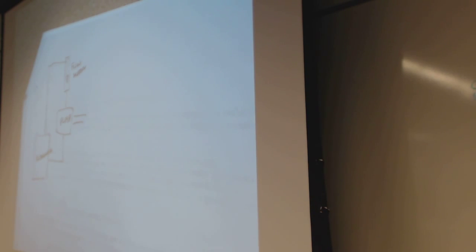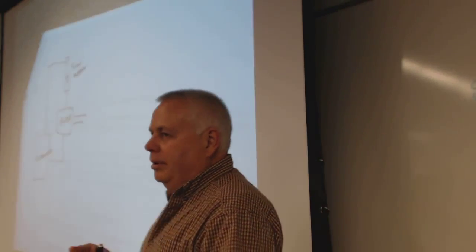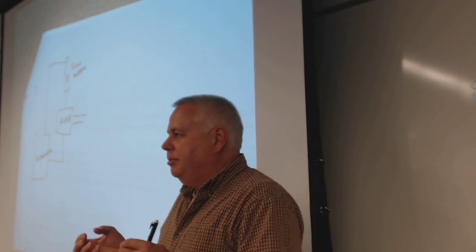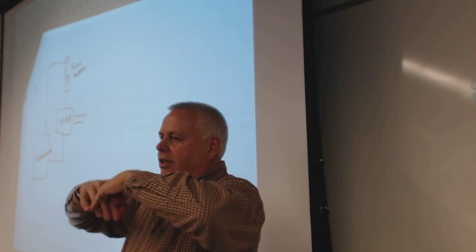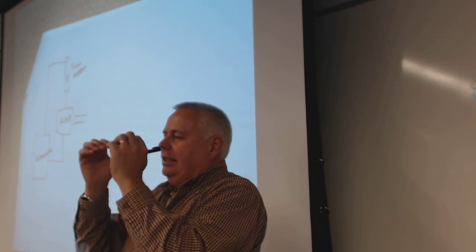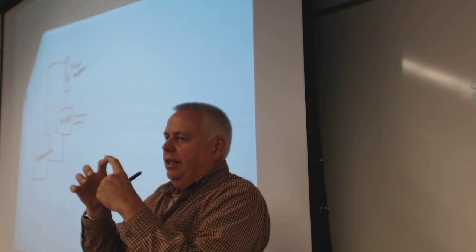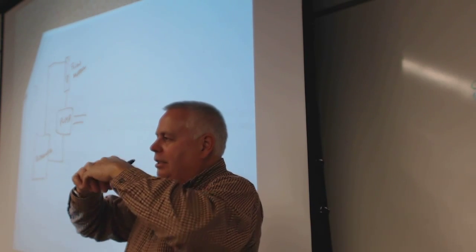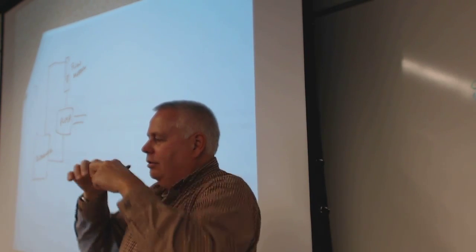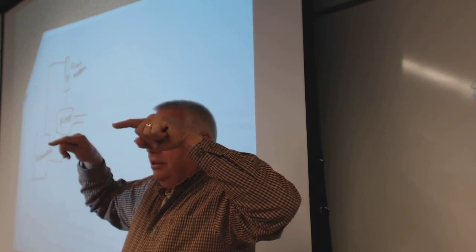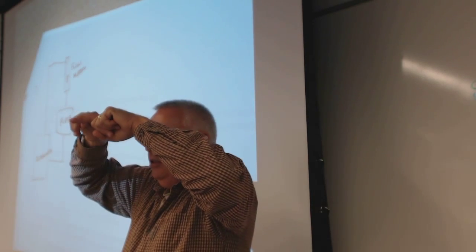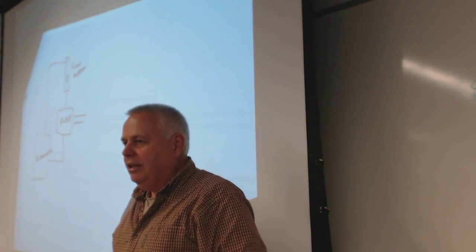There's a pump. The particular type of pump it is called a gear pump. It's like oil pumps in cars, the same thing. There's teeth that mesh and they turn around, and they're in a tight-fitting cavity. And as the teeth mesh, there's fluid in there, and the fluid gets carried around the empty teeth as they go around the outside, and where they mesh, then they kind of squirt the fluid out, if you want to think of it that way.